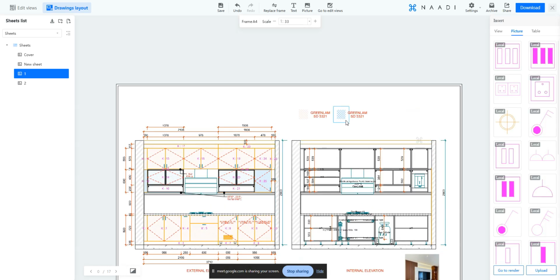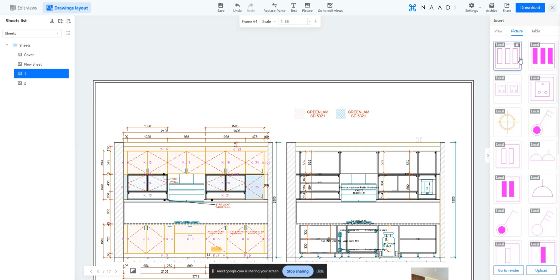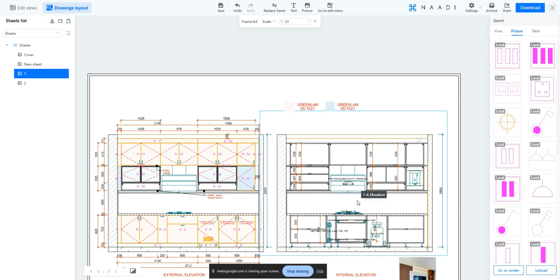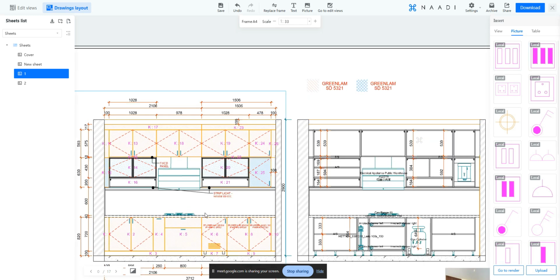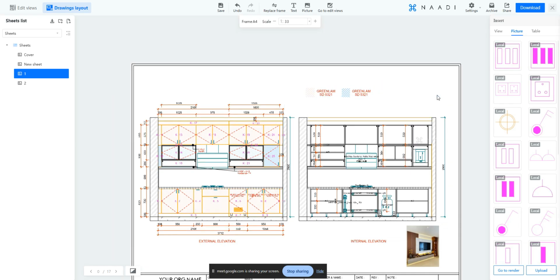And I've used a similar method to add a legend or the list of things for the electrical symbols. Not for this drawing, but for another drawing where I needed to mention what that symbol actually represents, right? For that, I zoomed in, took a snip of that and updated it. Or in your case, to make this process much more efficient, you can just download or plot your electrical symbol legend as one single image and save it in your system. In all your projects, you can just upload that legend image here. It will get updated and you can directly place it in your sheet.